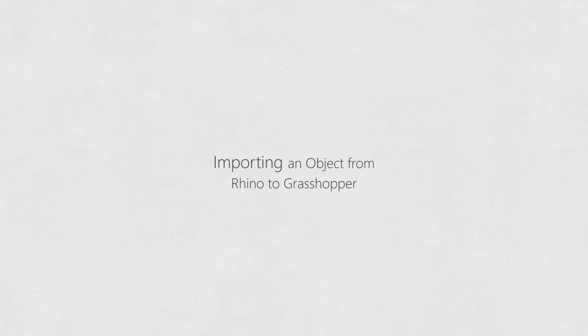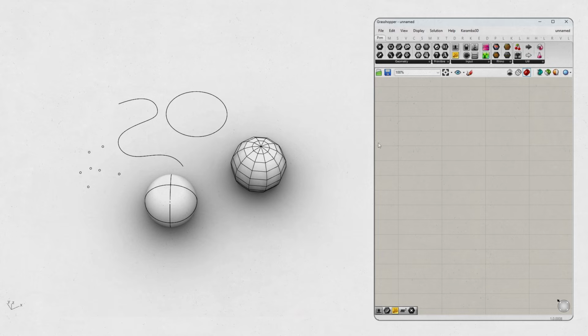So let's dive into something super important about Grasshopper. How do we actually bring in objects from Rhino into Grasshopper? Think about it. We often have a mixed design, where one part of our model is crafted by hand in Rhino, and then we want to parameterize another section. So we really need to know how to connect these 2 environments seamlessly.